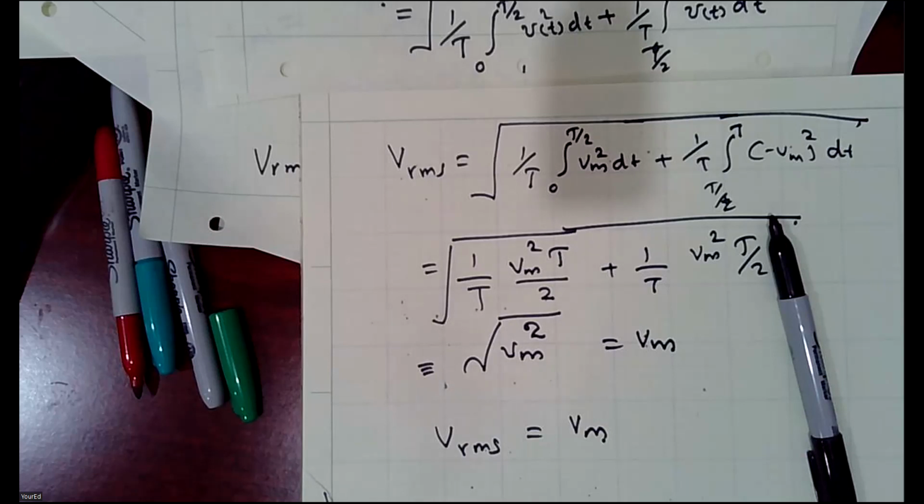In more general terms, when you use your ammeter or voltmeter, it will display RMS current and RMS voltage. When you measure the wall socket voltage of 120, that means your RMS value. So for a 120 volt AC bulb, the voltage that needs to be applied across the bulb is 120 volts. That is the RMS voltage. Keep that in mind. In another video, we will discuss loads and how to select these bulbs and everything from the shop. Then we will discuss those parameters in detail.